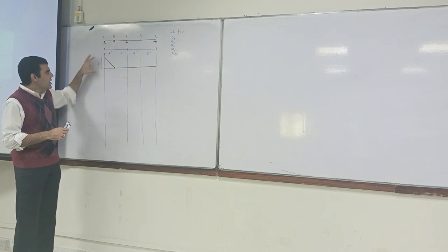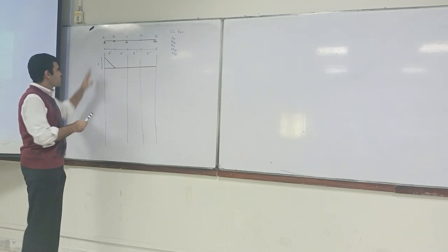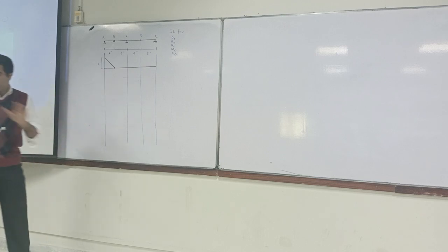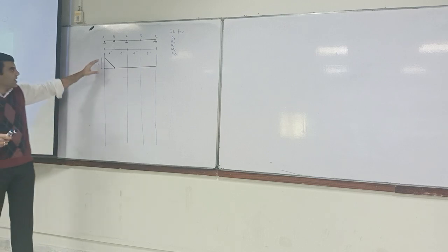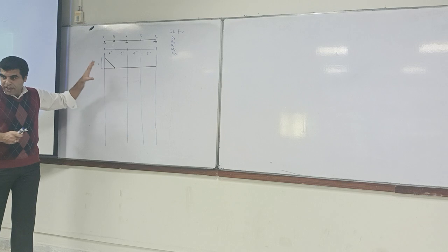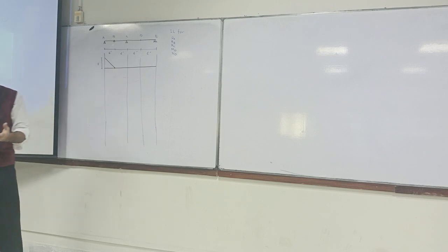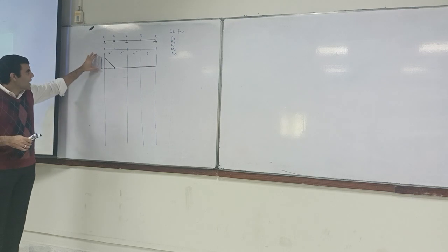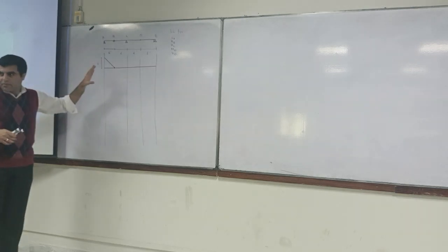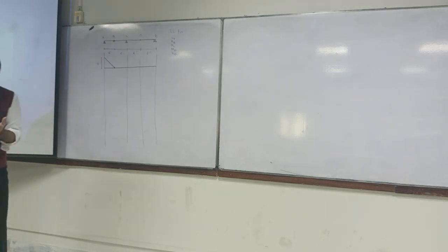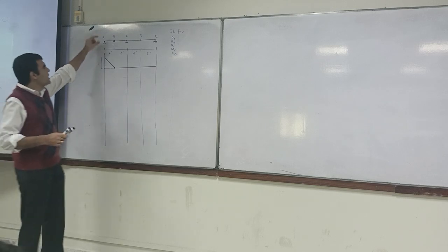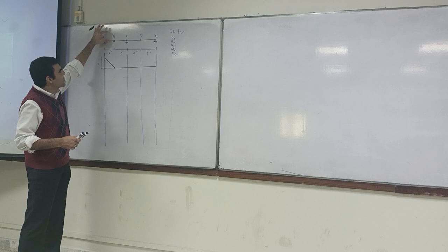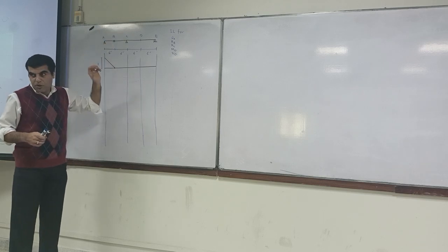So this is for RA. Everything is known. In the exam you will be required to draw it, and drawing an influence line doesn't mean you have to qualitatively draw it. You have to quantitatively draw it, and quantitatively how? By using the Müller-Breslau principle. You can also do the hardcore first principle, which means you actually place the unit load and then start moving it over here.